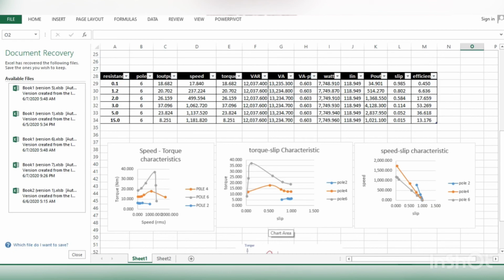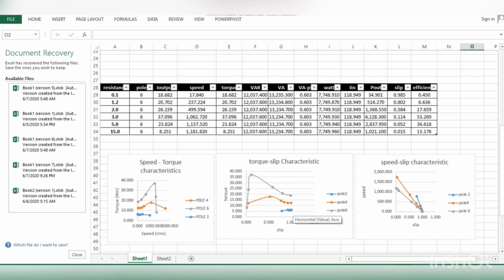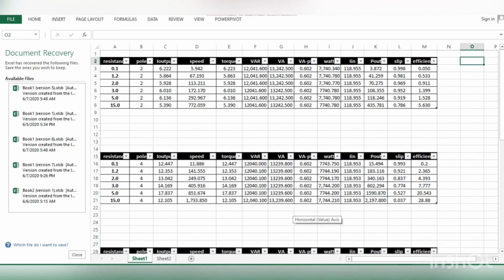As load increases above rated load, stator and rotor leakage reactance factors gradually become more significant in relation to this, such that torque gradually curves towards breakdown torque. That's all from me. Thank you.